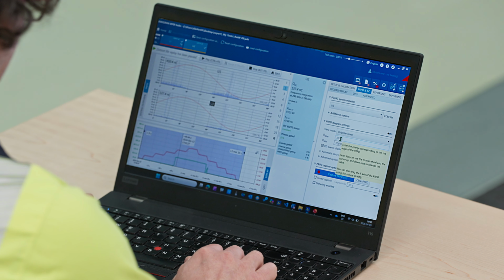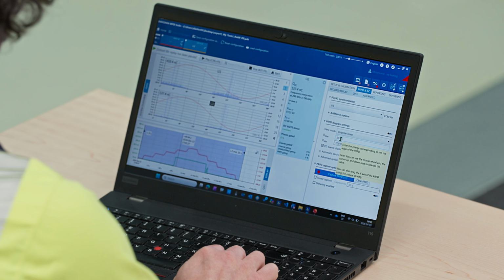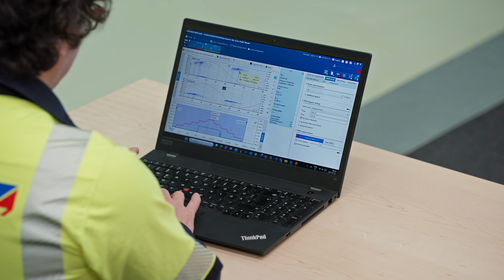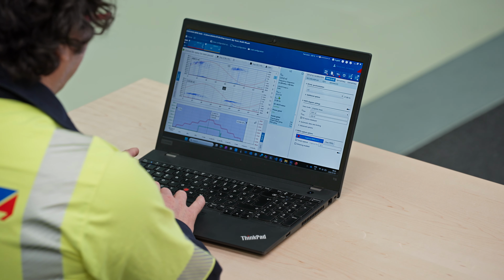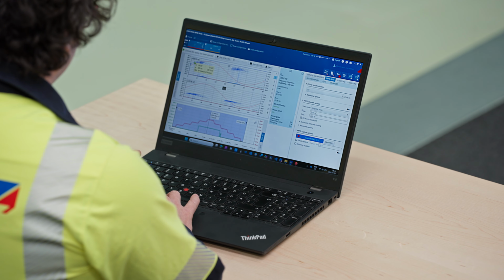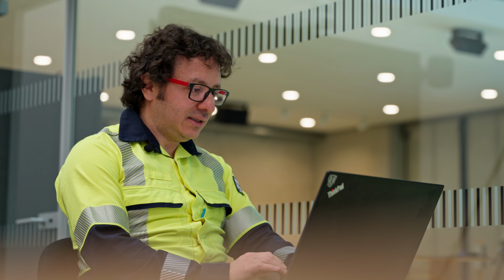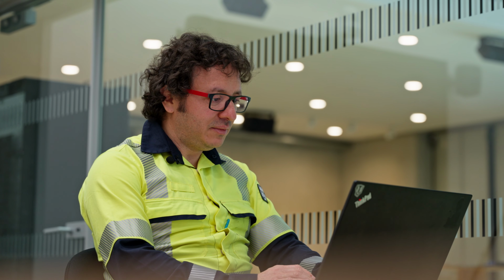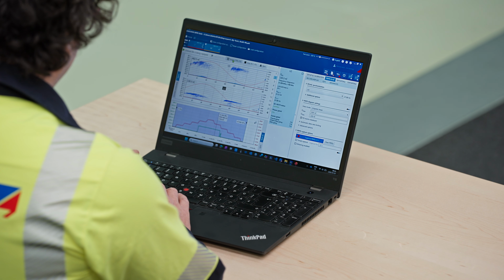It's very important to use a linear scaling when we are analyzing PD activity on rotating machines. So PD activity is extremely high. The test voltage now is 12 kV, and we are measuring close to 400 nanocoulombs. This is obviously not normal. However, this measurement might indicate problems in the end winding area of the stator winding.